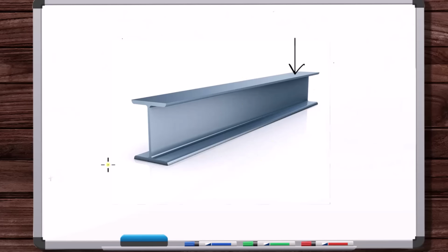Okay, so remember the process is we remove a component or a group of connected components. We haven't talked about connected components yet, and bring it into empty space. We remove the component either by undoing connections, so bolted connections or any kind of connection, undoing where the member or group of connected members are connected, and then bringing that body into empty space. Or we have the option of making a cut through the material. Or you could have a mixture of both. You could remove some connections and then do a cut at another location, so you could have removed connection points as well as a cut.